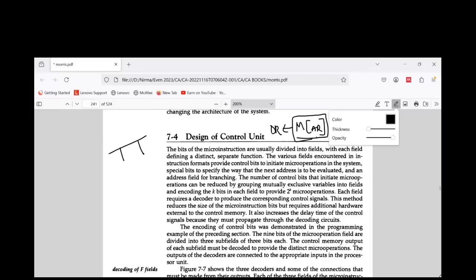Suppose you are asked to find out the control logic for the read input of memory. We identified those instructions which were on the left hand side of our RTL statements, and for those RTL statements, whatever was our control function, we designed a control logic circuit for it and provided it to the read input of the memory.